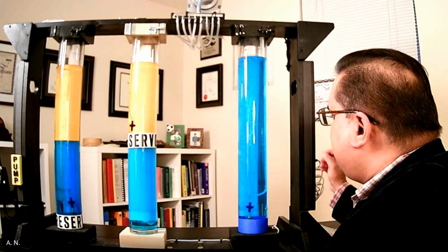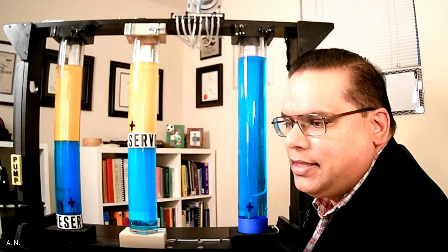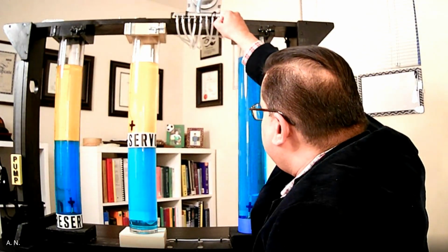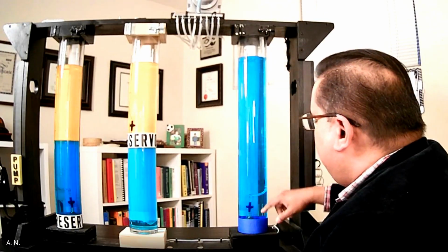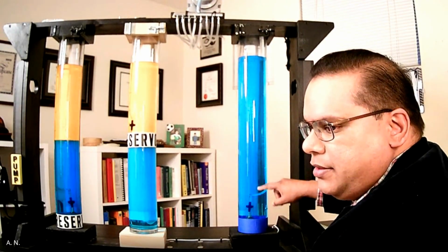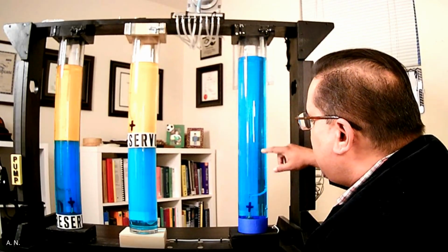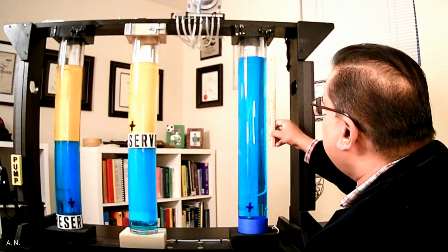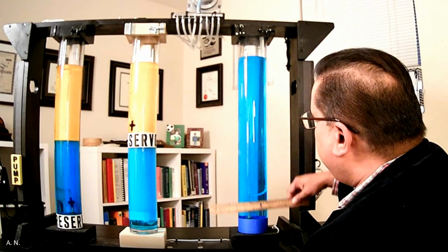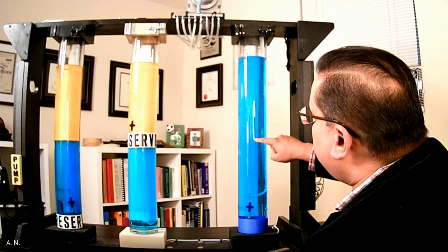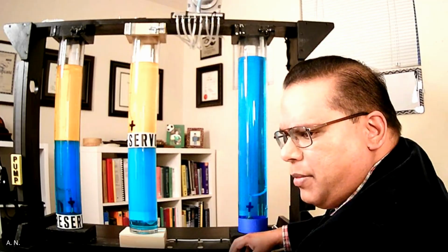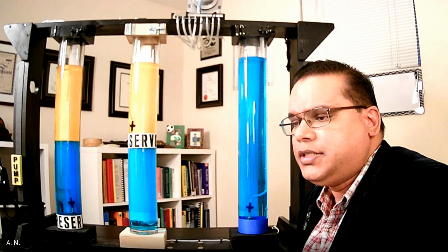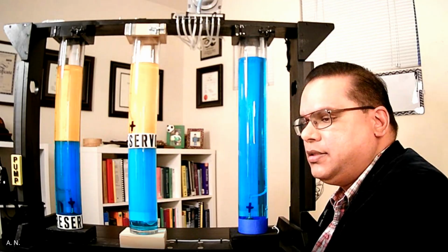All right. So what we have here is a liquid column. I initially lighted this thing like a Christmas tree, but then I couldn't see anything in the camera. But you can see that we can control the flow rate of this system, and basically you have bubbles rising. We can bring it down to single bubbles. As you can see, the bubbles are rising at approximately, this is a 12-inch ruler. So let's say you're looking from here to here, and you're seeing 1/1000, right? 1/1000, 1/1000. So that makes a lot of sense because 1/1000 is 12 inches per second. And that's what we know from the chemical engineering literature, 30 centimeters per second, the same thing.